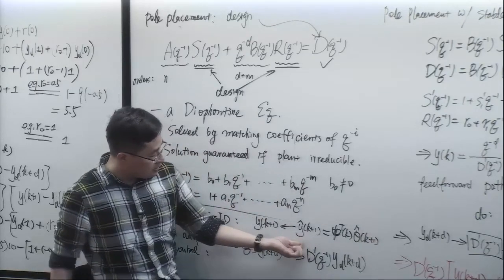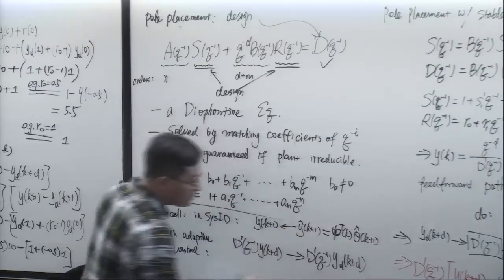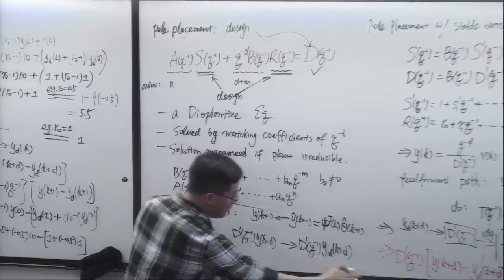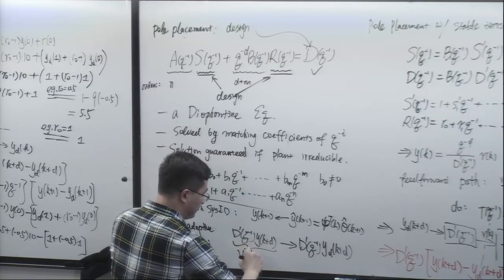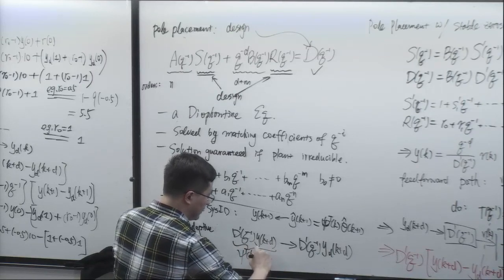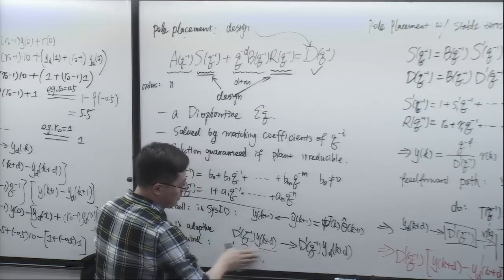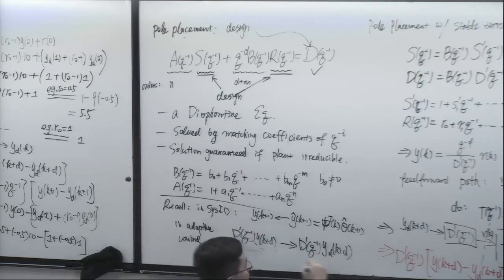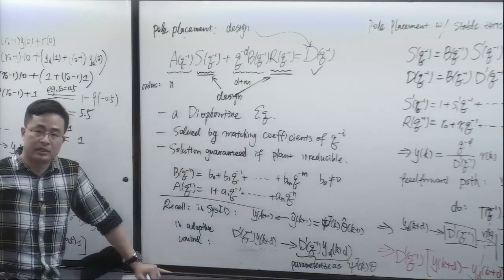We parameterize the plant, the process, with phi times theta. And then what we're going to do next is to parameterize this thing such that this becomes a new phi vector times a regressor vector. I will write it actually here. So what we want to do is to parameterize it as regressor times an unknown coefficient theta. So that's what we're going to do next.